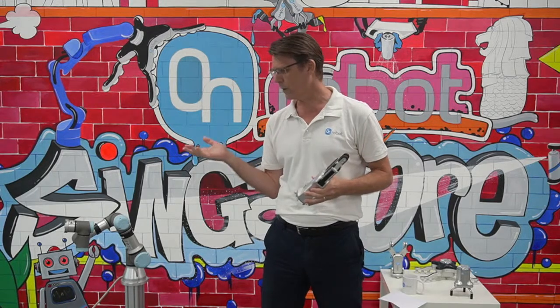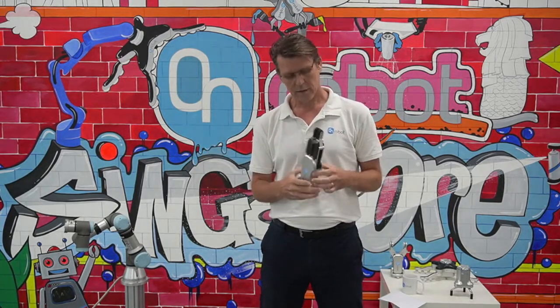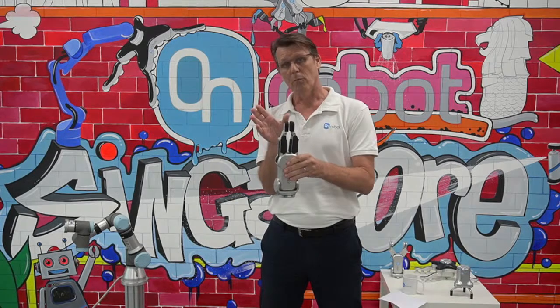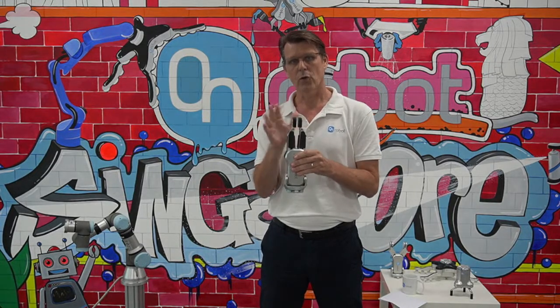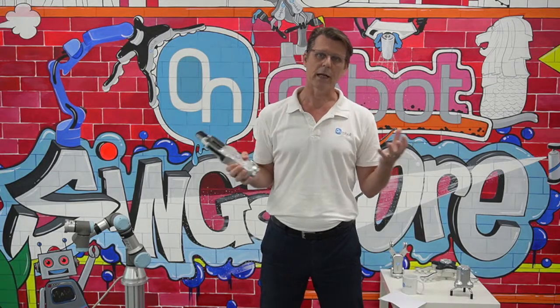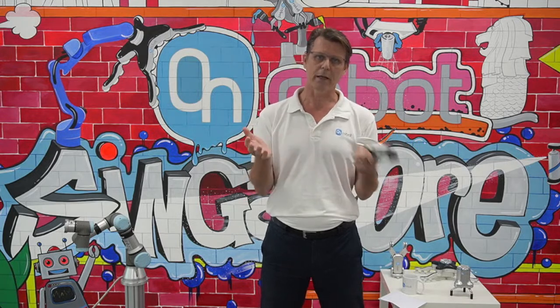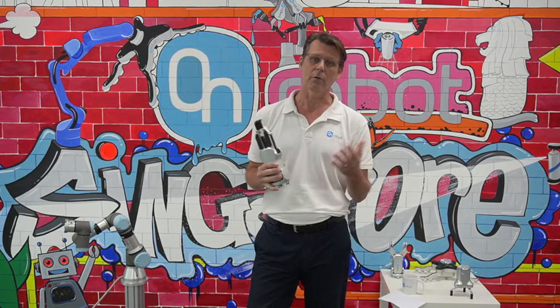I mentioned also at the beginning when I talked about 15066, if you have a gripper closing with more than 140 Newton, it's no longer considered collaborative, right? So you actually need to fence off your whole application. So look at 15066, it will give you a lot of guidelines on what to look for in terms of having a collaborative application, not just a collaborative gripper, right? Because having a cobot with a non-collaborative gripper, as an example, is not collaborative and you need to fence it off. So look at 15066, it will give you that kind of guideline on what you need to look out for.